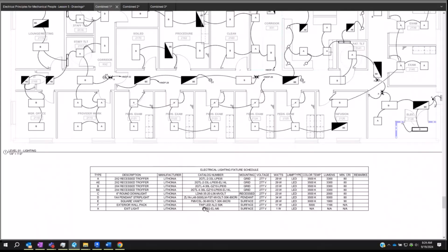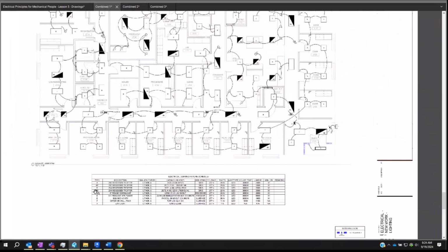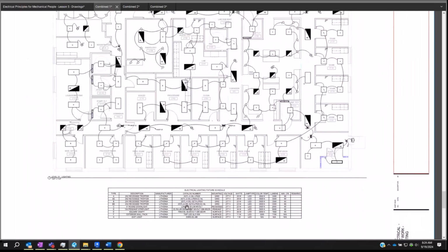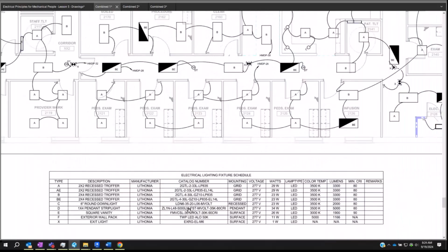And don't forget your lighting fixture schedule, by the way. Do you typically put your lighting fixture schedule on the lighting drawings, or on the schedule sheet? Depends. With the newer Revit versions coming out, you can actually do both now. Before that, you couldn't put the same schedule in two locations, so it always went on the lighting schedule.